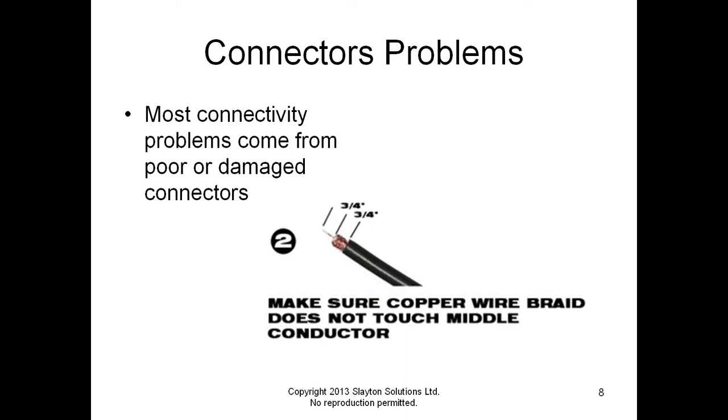And that's great. But you will have to know what kind of cable you got, and you're going to have to take those existing cables, cut off those old connectors, and put on new ones. You don't know who put the connectors on. You don't know how old they are unless you put them on yourself. You don't know what the story is. Cut the connectors off and put on new ones.